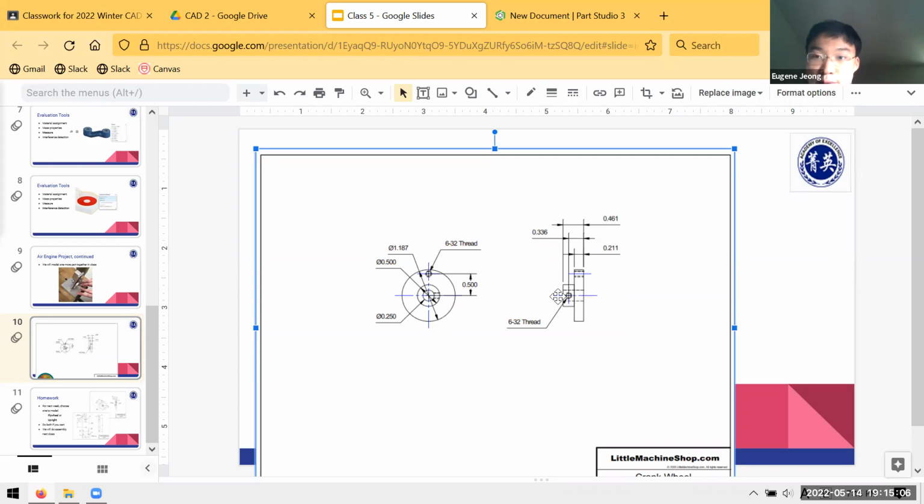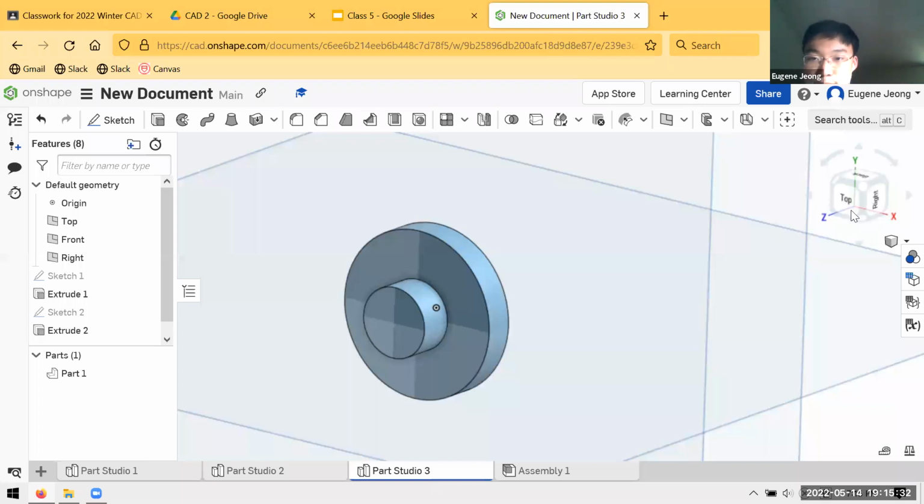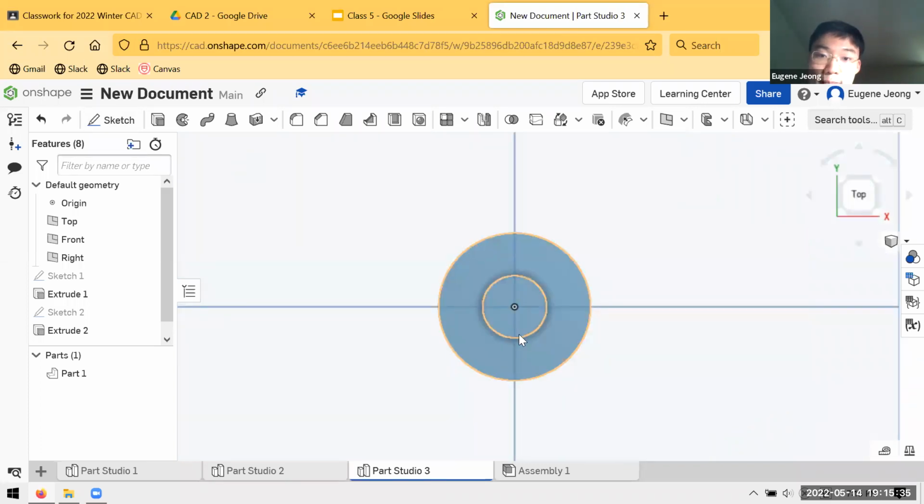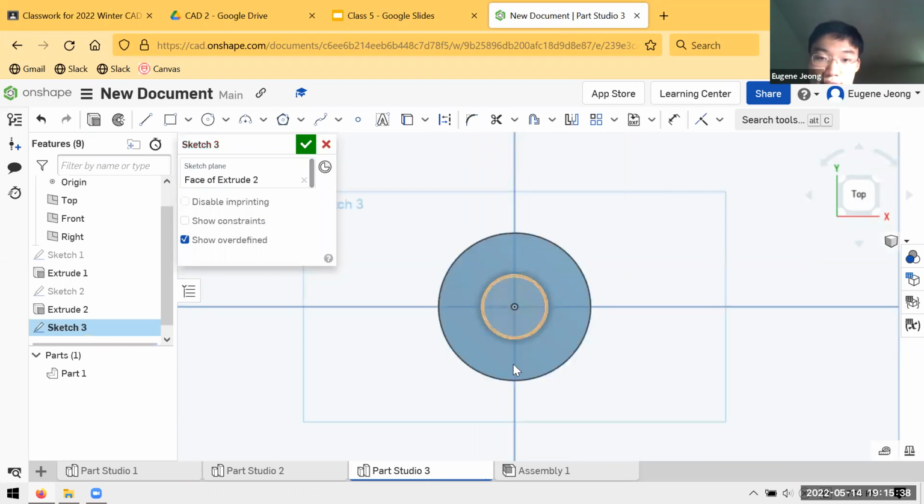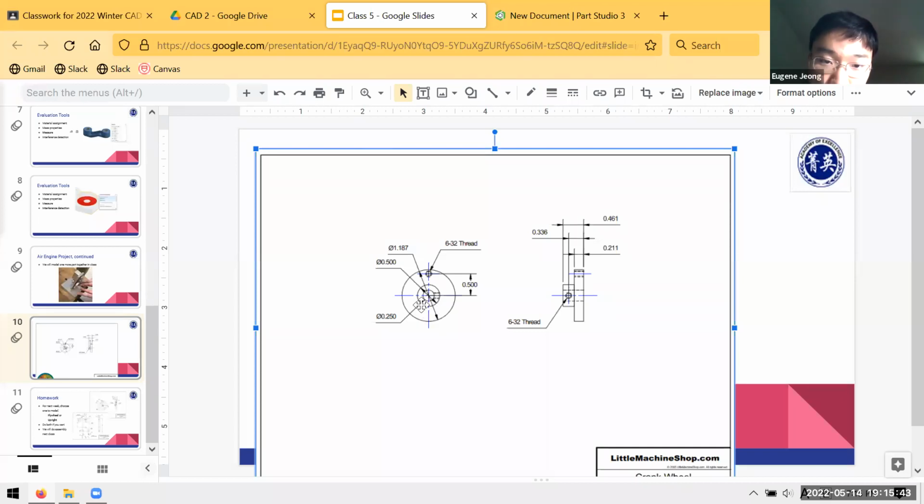And now I just have to add 3 holes to finish it off. There's the hole through the middle, which goes axially through the 2 wheels. There's one going sideways, which is for a set screw. And there's one more that goes through the flange, the brim of the hat, right here. So I'll add those 3 holes one by one, starting with the one on the top. Just create another sketch on one of these planes. Doesn't matter too much which one. The diameter of that hole is going to be 1/4 inch.